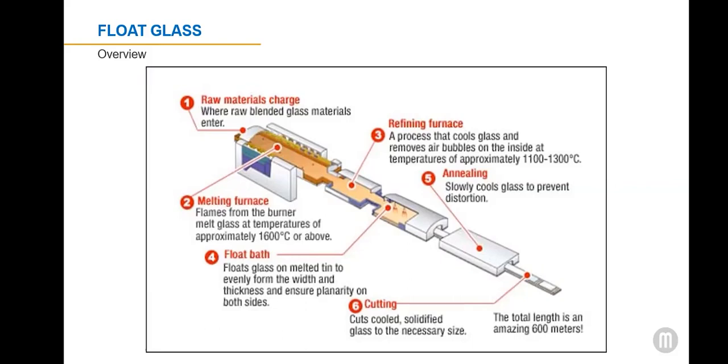The raw materials are mixed and then they enter the furnace. Once melted, the material becomes molten at around 2,800 degrees Fahrenheit. Gas and bubbles are removed in refinement and then cooled to control the viscosity. Liquid glass is then floated onto the molten tin at around 1,800 degrees Fahrenheit, forming a ribbon. Since the glass is highly viscous, it doesn't mix with the molten tin. This produces a flat contact surface. The thickness is controlled by increasing or decreasing the speed at which the glass spreads. Once leaving the tin, the rigid ribbon passes through an annealing chamber where the temperature of the glass is lowered from 1,050 degrees Fahrenheit to 480 degrees Fahrenheit. Further cooling takes place and then it's cut into sheets at the desired size.